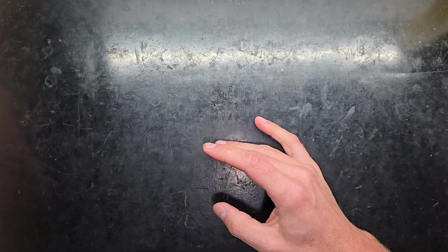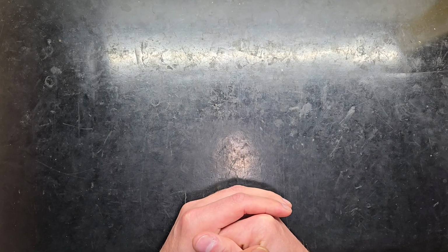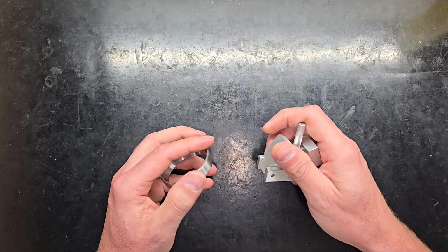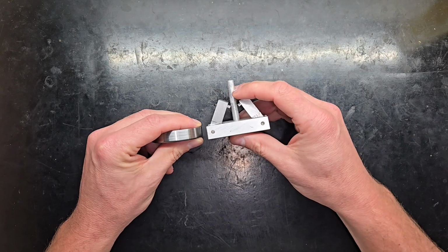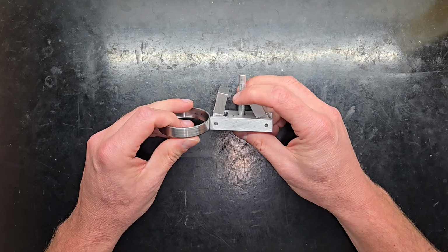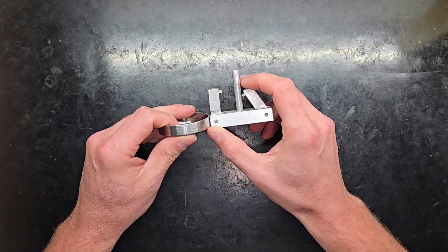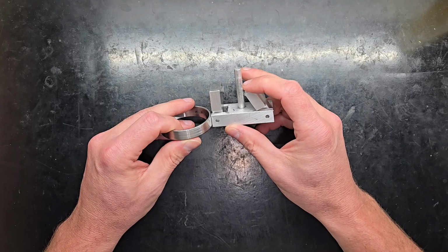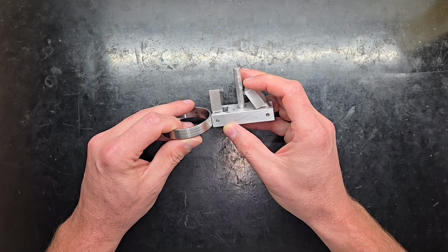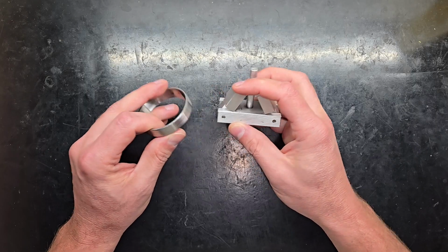Corrosive wear is less common today, but it is still a problem. Firearm manufacturers have spent a lot of time and a lot of money working on different coatings and treatments to help keep corrosion and rust away. Another type of corrosive wear is what we call a galvanic couple. Galvanic couples can happen between dissimilar metals, and aluminum and steel are very common. You need an electrolyte in the middle, but you create a galvanic couple and the aluminum will slowly be eroded away, but the steel will be left in place. This is a larger problem in the automotive and aerospace industries, and less of one in our firearm space.